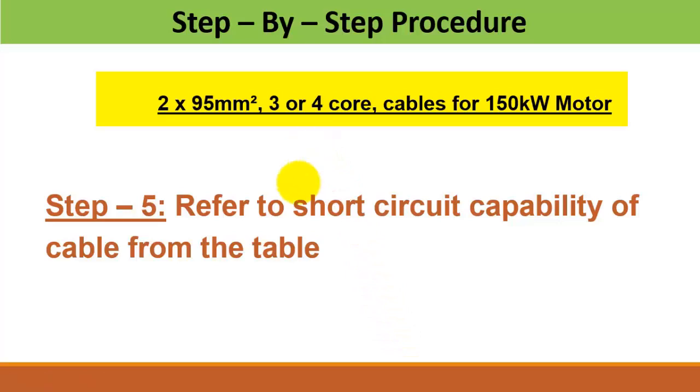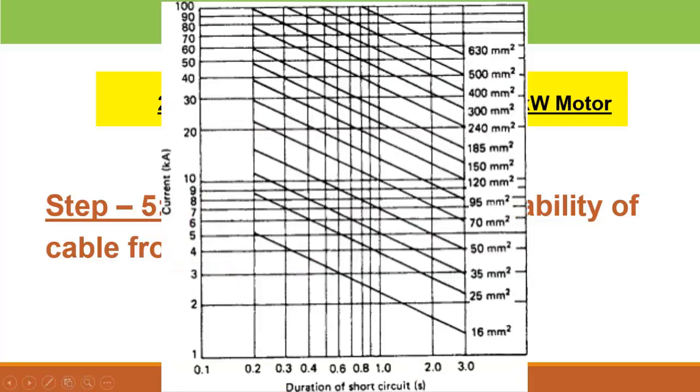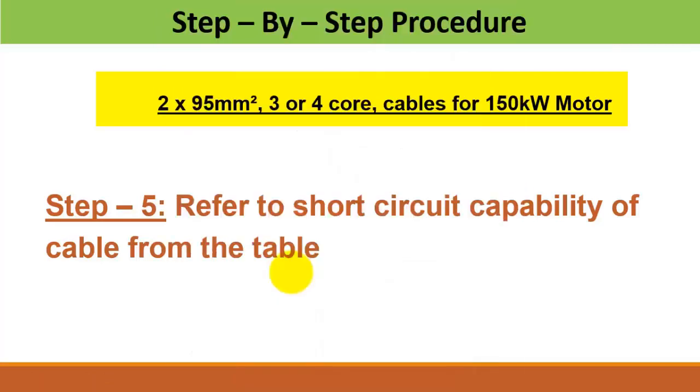for the 150 kilowatt motor. The last step is to refer to the short circuit capability table to check the maximum short circuit withstand capability of the selected cable size. I hope you understand how to size the cable.